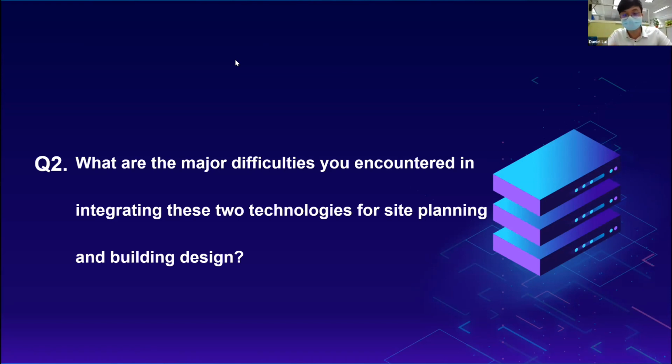And we solved it by using the IFC intermediate step to convert the model twice in order to save the project in a compatible version for the later ArcGIS environment conversion and integration process.